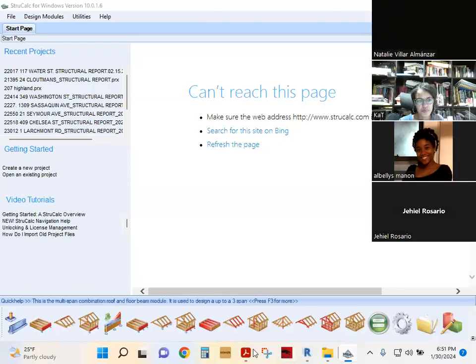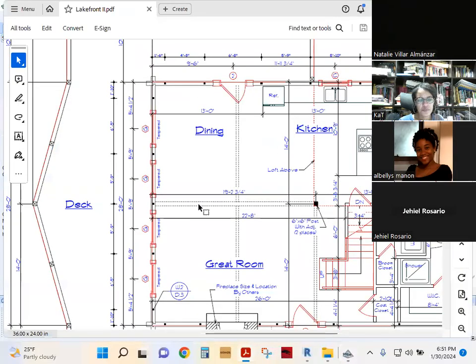All right, so we have a project for a log home that's gonna have an open concept. The span is over 28 feet. As you guys know, lumber is very expensive, and to get TJIs or deep I-joists that will go all the way through, that's a lot of money. So we'd rather put a column here and a column inside this wall, put a beam, and support our joists in this piece. So the joists are gonna be half of that span. If it is 28, it's gonna be 14 feet each.